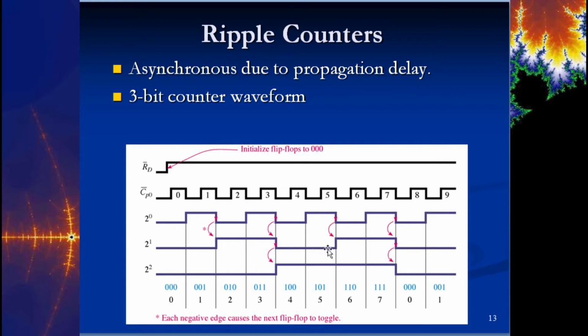So in the Kleitz example here, he's showing it happening sort of instantaneously, but however long the propagation delay is from this thing going from high to low, and from this changing from the input to the output, whether it's 10 to 20 nanoseconds, whatever it is, there's a slight little shift there. And that's going to become important because the more flip-flops that we put in the cascade here, you're going to keep building that propagation delay with each output, right? And so that can be a problem potentially.